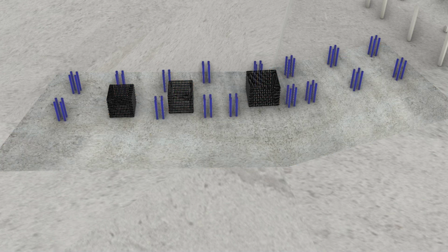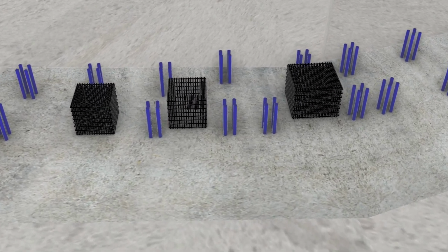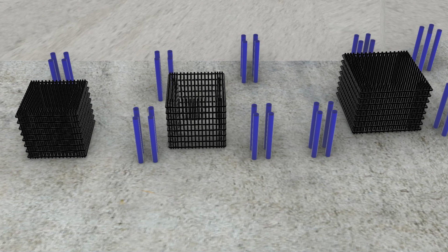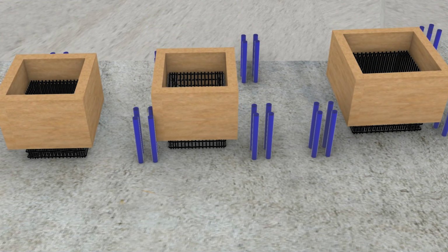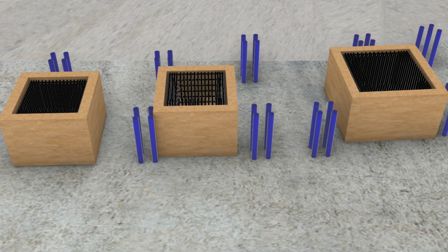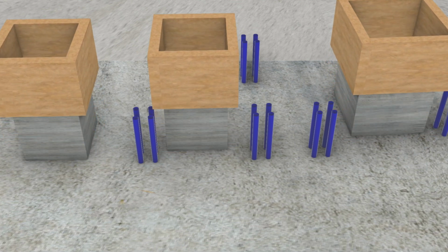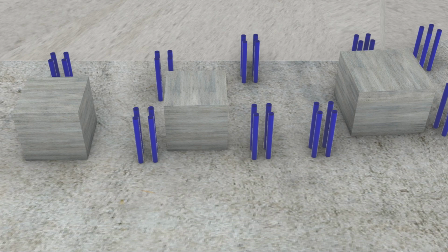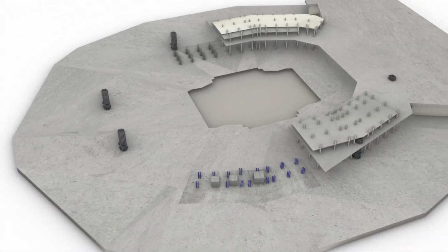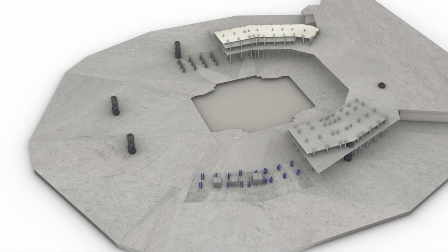Mechanical couplers were used to connect vertical rebars between segments, ensuring full stress continuity without reducing cross-sectional area. Before casting the next segments, bonding grout was applied to the surface and vibration was used to eliminate voids and ensure proper consolidation between layers.